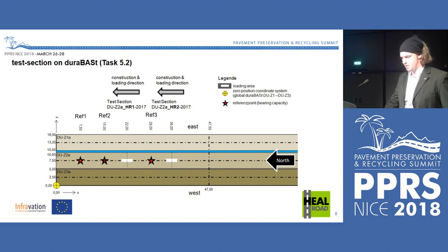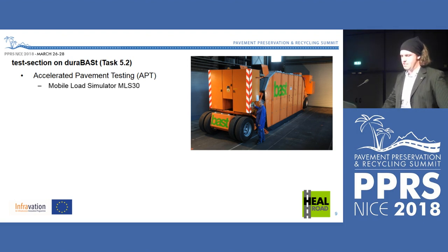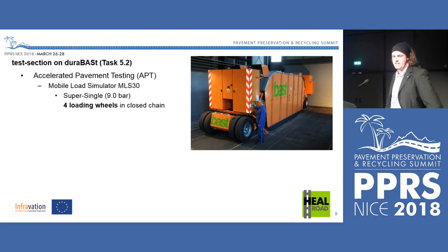So we had these 2 loading sections. If I talk about loading, we used an accelerated pavement testing program, and in BUS we are using the mobile load simulator MLS30. The MLS30 is equipped with 4 super single loading tires in a closed chain.